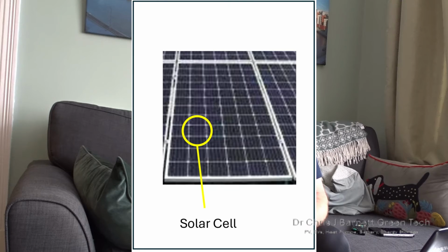First of all, the solar panels on your roof are made up of individual solar cells. These have been getting bigger and getting higher quality with the movement from amorphous silicon, which has lots of grains in it, through to single crystal, which means the electrons can travel through it easier, so when you want to extract your current, it has fewer boundaries to transport across. So think about this as having a pipe with lots of little connectors in it. There's more chances of leaks. So if you have one big solid pipe, it's better. So that's one improvement, hence one of the reasons why silicon solar panels have been improving in efficiency.